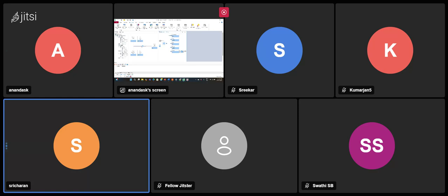Coming to the CAPL test node: for example, with logging, you can make a CAPL script to create the logging file and open it automatically. For that we can use the CAPL test node; there we can write our CAPL script. And the XML file is for diagnostics, UDS, where we set some values. For that we can create an XML test module. I did not work much on that, but I worked on the network node and the CAPL test node.